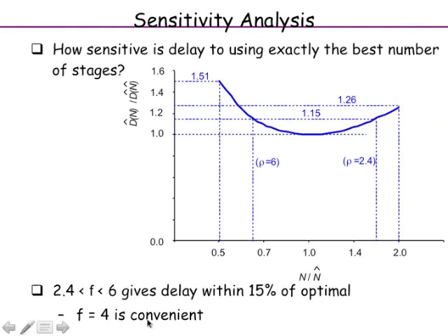And so we use this rule of thumb that the optimal sizing of a chain of gates should be such that the effort by each gate is 4. Instead of saying 3.5, 3.8, you just say optimal effort is 4, because the answer is kind of close to that. And if you use 4, you will not be too far off.